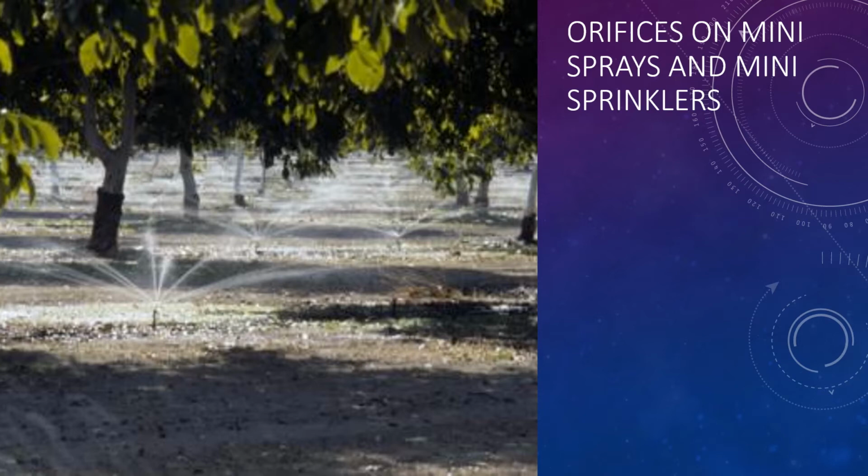And so the size difference between those two is huge, but there was so much that it plugged the filter. And so that had a dramatic impact on not only the filter, but also the drip lines were filling up, which we'll talk about shortly.